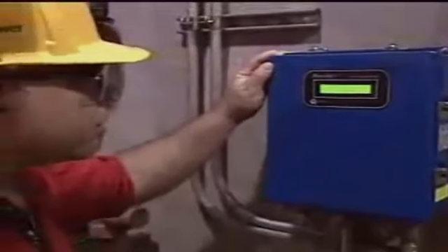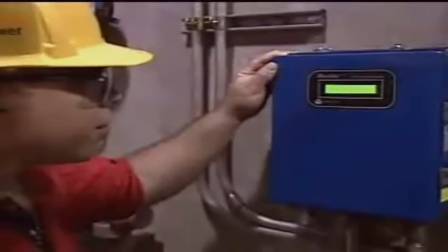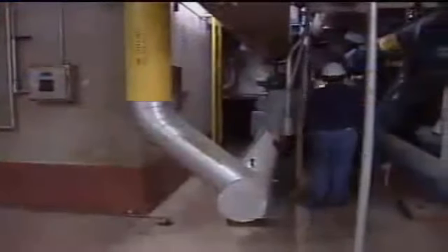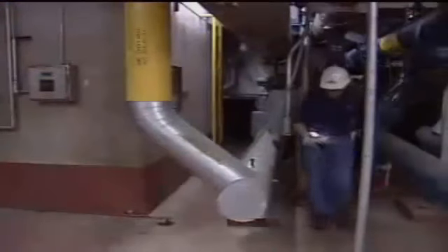If an air leak is suspected as the cause of the low vacuum condition, you should check the airflow monitors or air leak detectors in the air removal system. If the airflow reading is higher than normal, the condenser and every system connected to it must be carefully inspected so that the source of the leak can be found and corrected.